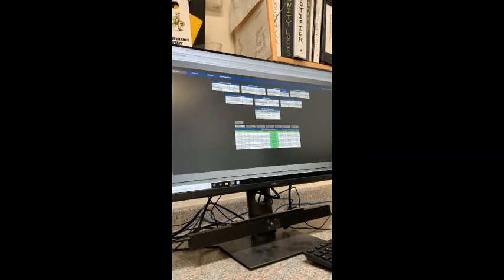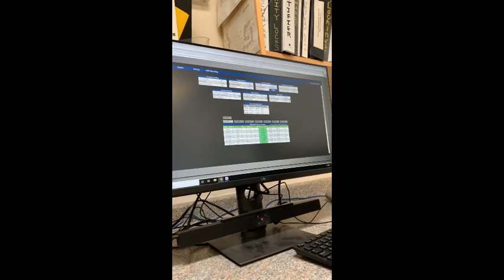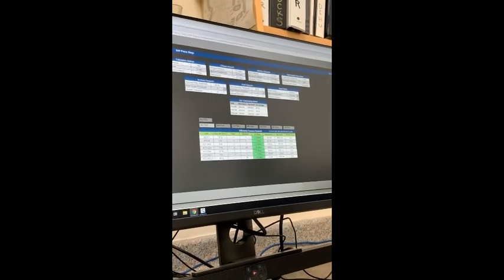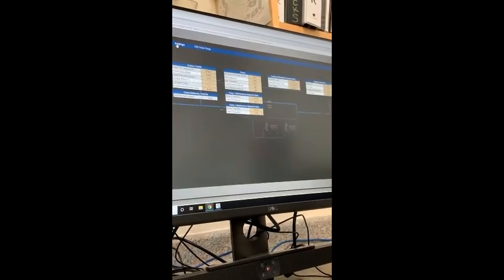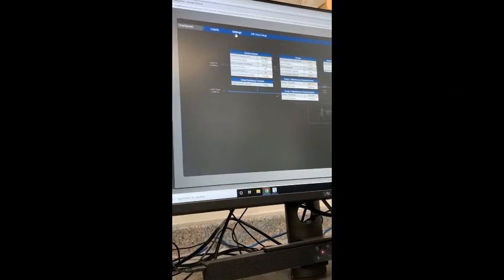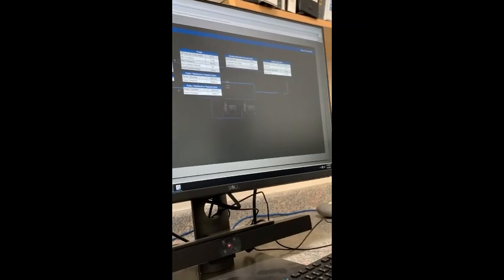But it will go from an initial set point of 5 down to 0.5 or up to 20, depending on the demand. Yeah, that's what I was kind of wondering, the range. So when we look at it, we can kind of get an idea. In this pop-up, there's also a page for the settings. So in here, you'll see alarm settings.